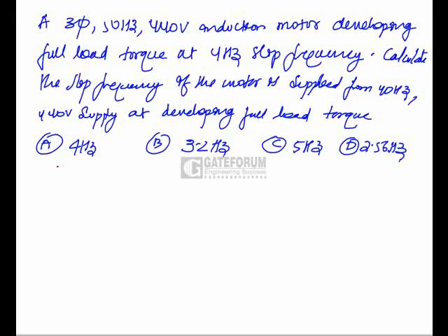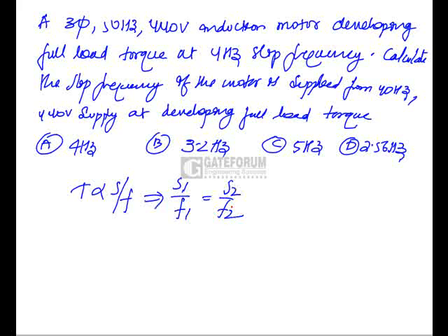Next question: a 50 Hz, 440 volts induction motor develops full load torque at 4 Hz slip frequency. Calculate the slip frequency if the motor is supplied from a 40 Hz, 440 volts supply, developing full load torque. Earlier it was supplied from 50 Hz, now from 40 Hz with the same voltage rating. We know that torque is directly proportional to S by F, so S1 by F1 is equal to S2 by F2.